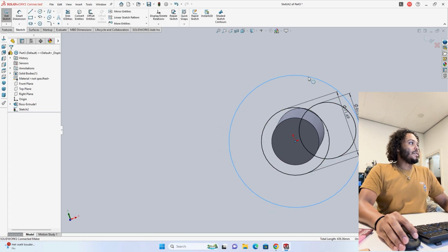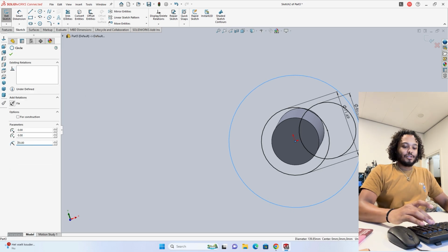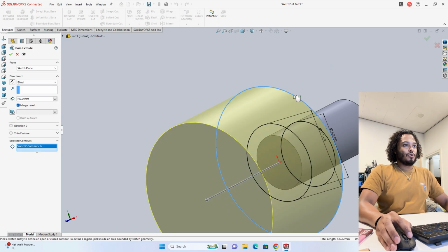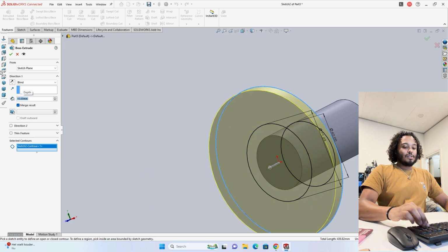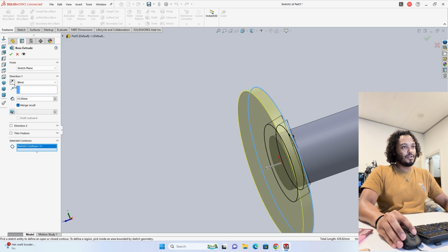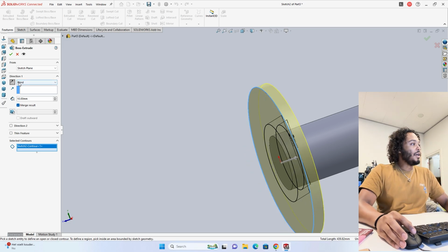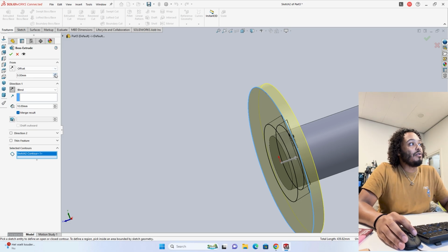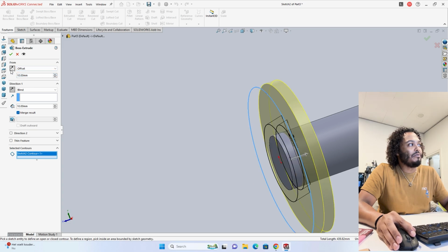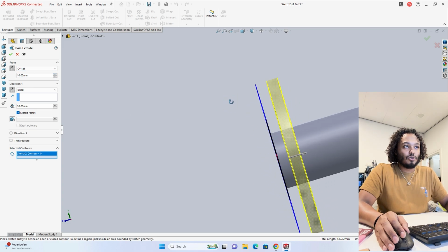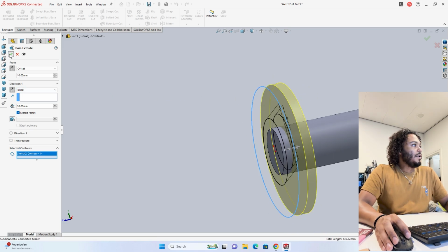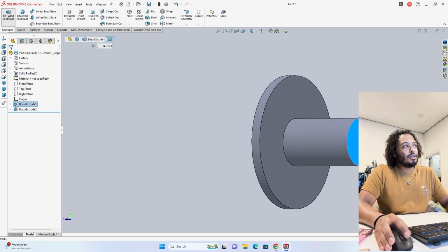So let's also check this right here. Let's just put it at 70. Then we have like some square hole dimensions, I guess. And then we're gonna take this line right here, let's say 10 millimeters, and we're gonna make it in the other direction. So if it is looking into that direction, you can flip it around by hitting that switch. And then we're also gonna make it offset, because we don't want it to protrude from this surface, but we want it to go inward a little bit, and now it is offsetting into the wrong direction. So again, you can make it go into the opposite direction, and about 10 millimeters should be sufficient in this manner. And then we're basically gonna do the same on the other side.